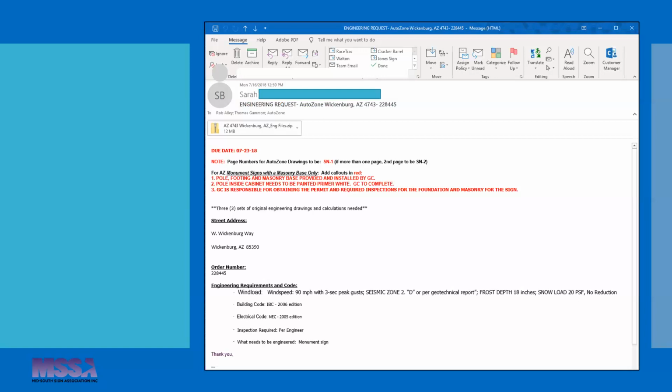That is very helpful for us because depending on where the sign is going to be installed, the building code may change depending on the address. And in particular, the wind speed could change. An example that comes to mind is the Tampa, St. Petersburg area. There are 3 different wind zones across the city. So if we don't know the street, or depending on how close it is to the edge of those zones, sometimes even the physical address on that street, the actual building number, we don't know which wind speed needs to be used. And so we'll always go with the most conservative to make sure that everything is covered, but often more conservative means a little bit oversized, and that could mean additional cost.